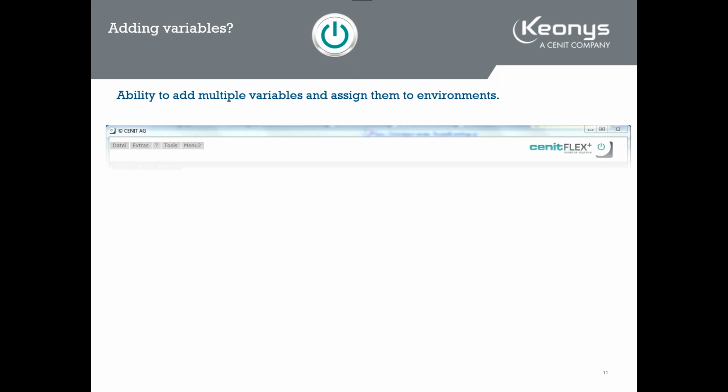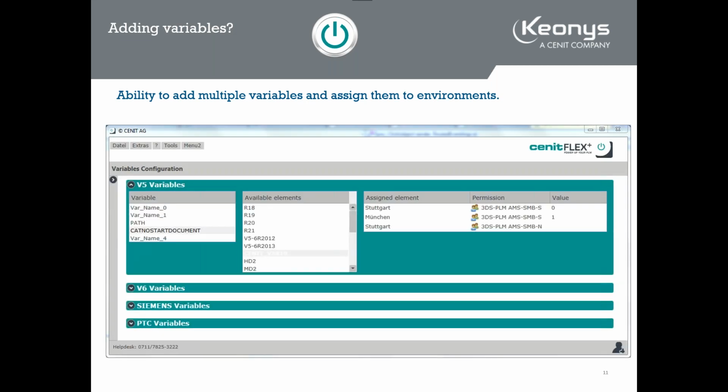Do you need to define a specific variable for your different products? Sure, there is a way, and that's right in the backbone in the administration mode. There is a menu for that where you can define, assign, and save variables. As you can see here, for example, for this V5 variable labels, I usually create some variables. You can create, for example, this famous variable DS licensing or DSLS config. You can assign it to a version of an environment or a product that is installed.